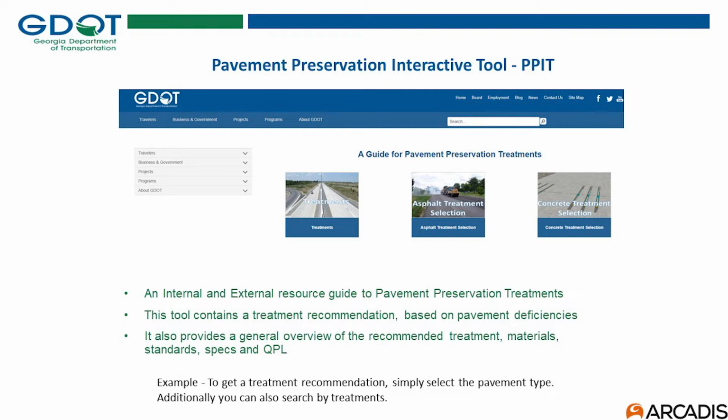It's not going to pinpoint exactly what you should do to this road. It's going to give you choices. And choices are based on the condition of the asset and the parameters of it. Is it in a curb section? Is it in a rural section? So those of us that have been learning about preservation know what treatments work where and which ones you steer away from.